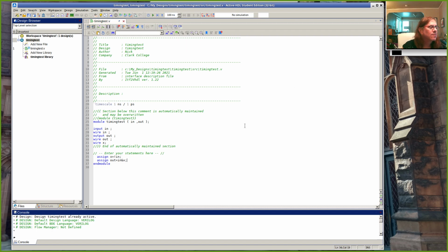Is wire similar to a variable? It's basically declaring a variable, and it's saying it's just a plain old signal, so it can be given a value, but it doesn't remember what the value is. We're going to have a new way to declare variables later today, which is to say register or reg, and once we have that, it'll make more sense why sometimes we say wire.